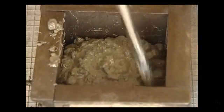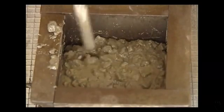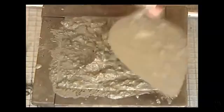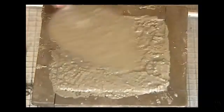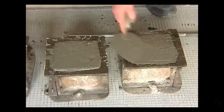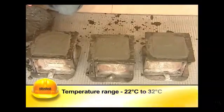Each layer should be compacted with 35 blows. The tamping rod should enter the previous layer while tamping the subsequent layer. After compacting the top layer, the surface is made flush with edges of mold using a trowel. The mold is covered immediately with damp Hessian cloth and left undisturbed for 24 hours. Site specimens should be stored in 22 degrees Celsius to 32 degrees Celsius.